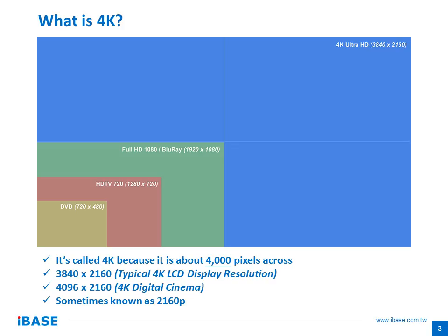Right? Now there's also 4K digital cinema. If you go to your favorite movie theater and they have 4K high definition digital cinema, that's actually 4096 by 2160. So a little bit of a difference in resolution there. Not particularly critical, but those are the 2 common resolutions that are commonly described as 4K. Now 4K is also sometimes referred to as 2160p. And the reason it's referred to as that is that it has 2,160 horizontal lines in the screen area.